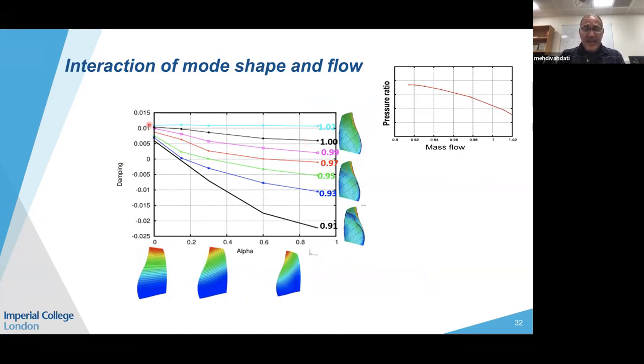You can see that for a blade which has pure plunging, i.e. just doing a bending motion, the aerodynamic damping is quite independent of the mode shape.